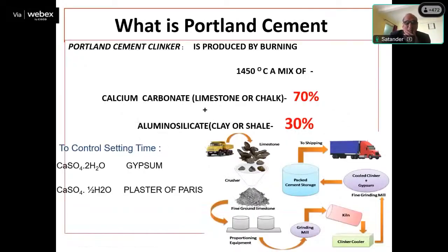Next, come to the cement part. First, what is cement? If you try to understand, 70% limestone, 30% clay we take, calcine at 1400, we get tricalcium silicate. When you grind, it will immediately set within 2 minutes. To control the setting time, we add plaster of Paris or gypsum. Correct? This is just brief I am saying.